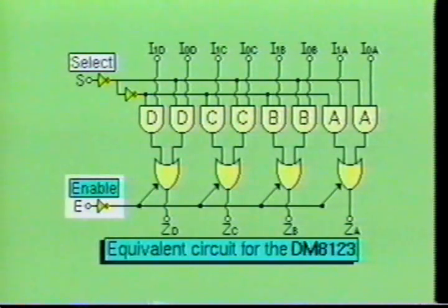When the enable input is at the logic 0 level, the outputs are conventional TTL. However, when a logical 1 is applied, the outputs assume a high impedance state. Both upper and lower output transistors are turned off. The resulting condition allows many devices to be connected to a common bus line without loading down or being loaded down by other devices on the line.